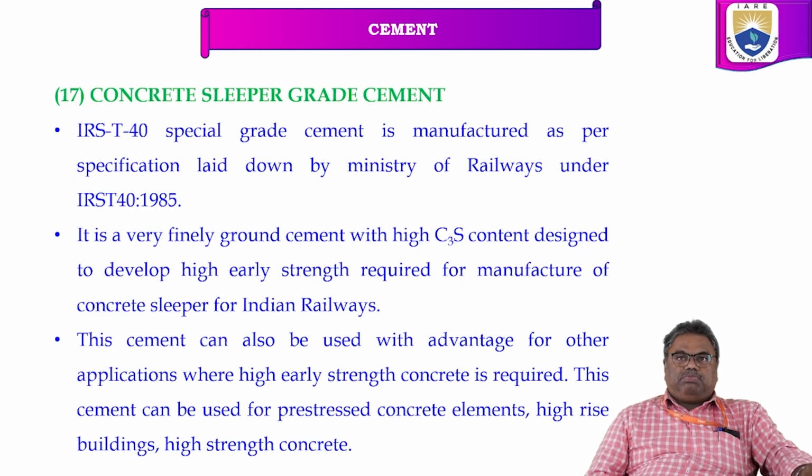Next, concrete sleeper grade cement. The name itself says it is for concrete sleepers. We use this type of cement to make concrete sleepers, based on the Indian Railway codes, IRS T40 1985.